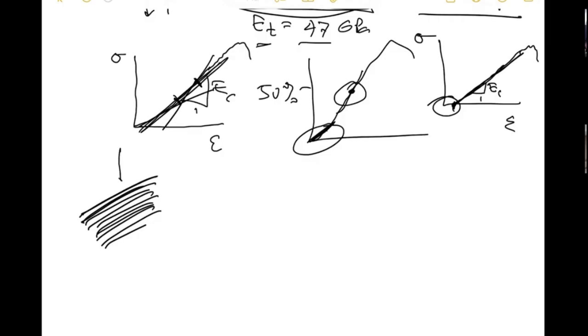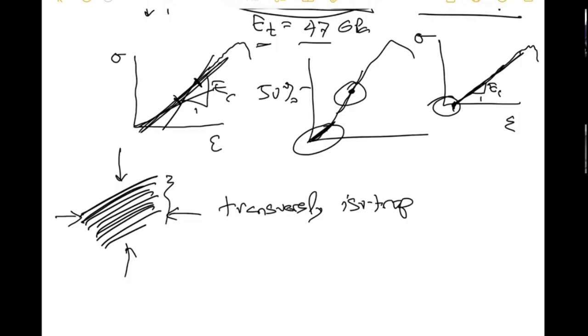If you squeeze it this way, it's going to be different than if you squeeze it this way, the way it responds, because it has to do with this complicated orientation. So the formability is going to be more complicated. And so instead of linear elastic isotropic, you say it's transversely isotropic. And basically, if you use theory of elasticity and you assume certain symmetry that corresponds with this, you come up with, I'm not sure, it's either 5 or 6. You get like 5 independent constants.